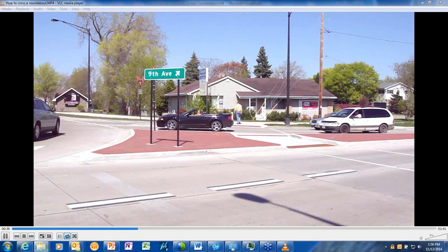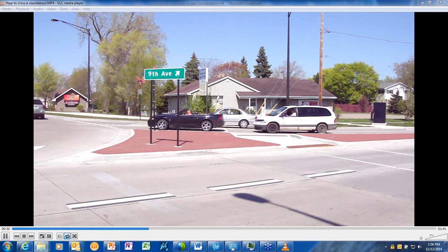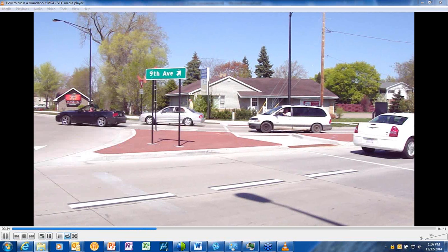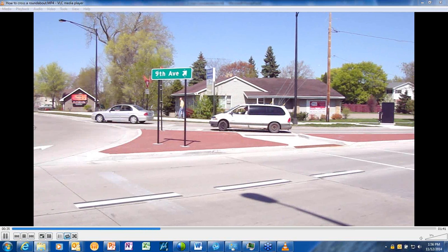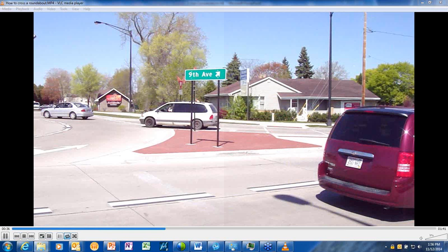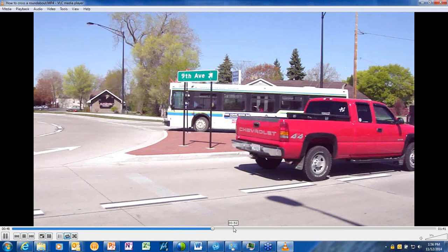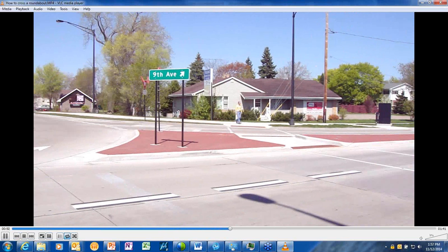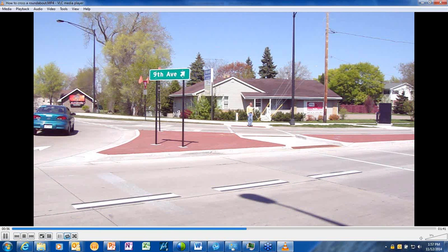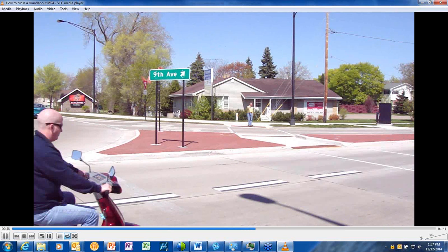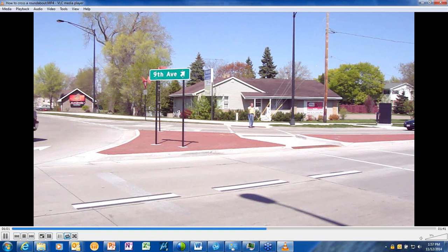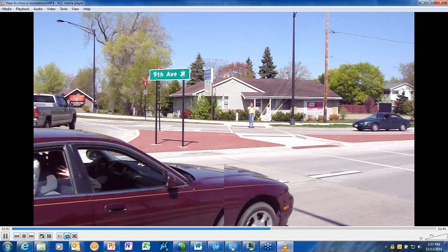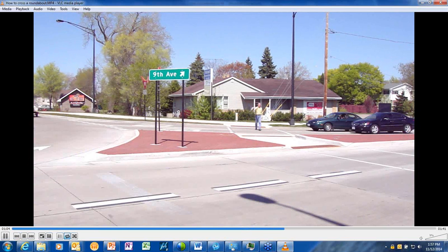The point is that hundreds of roundabouts have been built, with very few pedestrian-involved crashes, and so we think that the safety is reasonably good for roundabouts and pedestrians. It's just the visually impaired question is a tough one to address without thinking we should add more devices. And you don't always know. You've got to wait till they stop. It's not safe until they yield.